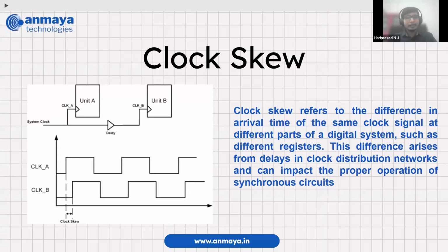We go for some kind of counter logic, right? So that counter logic based clock we usually connect to our logic, right? So now what we have done, we are mixing the data path and clock path, right? Whatever the generated clocks are there, let's say counter based or any data based generated clock, we shouldn't use it in the sensitivity list.